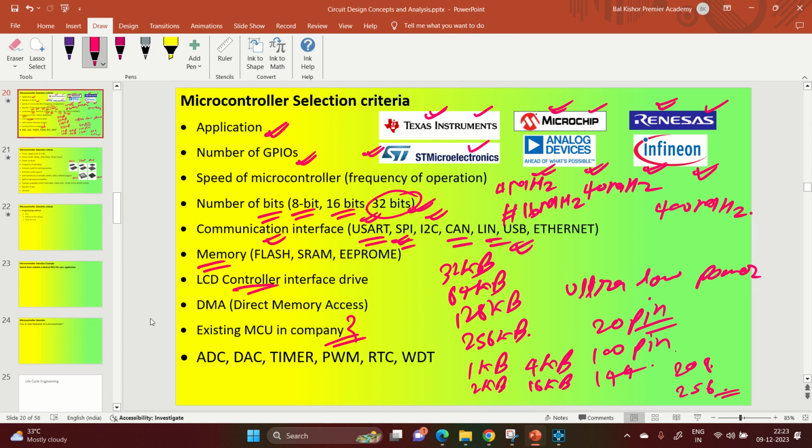Even if that MCU is on the verge of end of life, or not recommended for new design, it is still best, because you can take that microcontroller as a reference and search against it. It is very easy to find a microcontroller having the parameters of existing microcontrollers. This gives you a reference to find a different microcontroller.